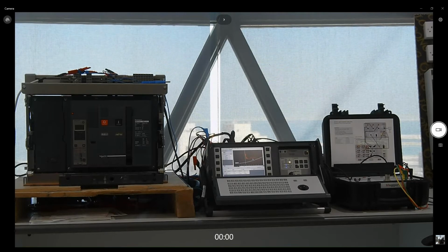For example, are you moving more than you should be, what we call stroke, or are you moving at a faster speed, or are you having a lot of bounces at the end or at the beginning of the operation, meaning you have something maybe loose, it's not being stopped or initiated correctly.